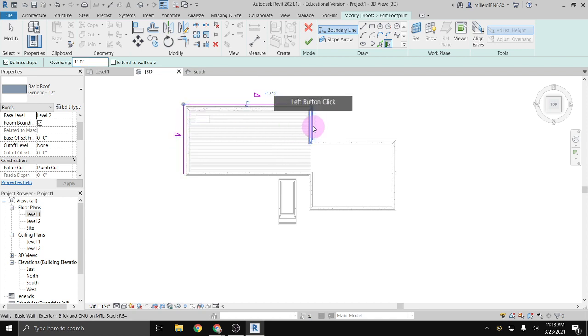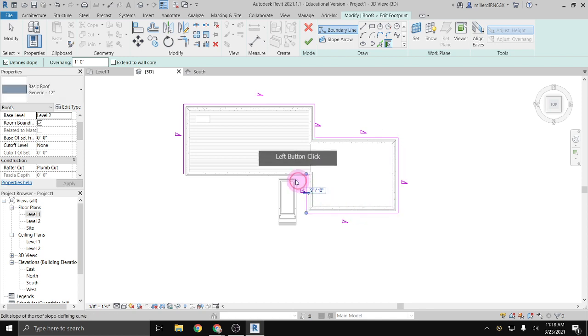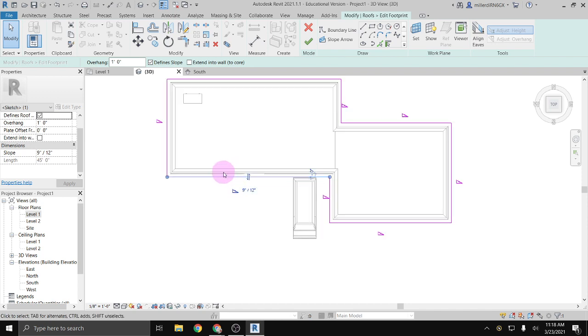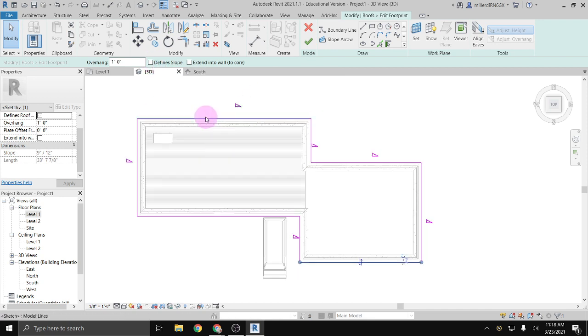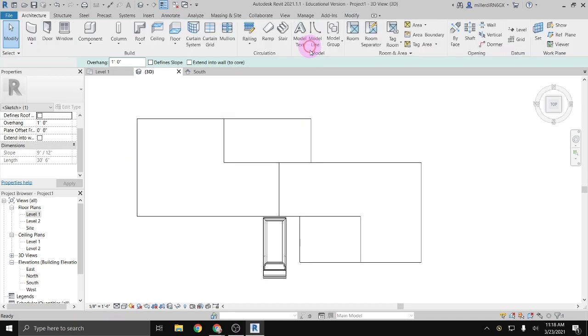And now it'll just automatically place all of these lines on the walls I pick, 1 foot off. Hit escape, and then I can even click on these again and say, I actually don't want this one sloped, or this one, or this one. So I can define these as I go, which is just so cool and crazy, and I could change them afterwards.